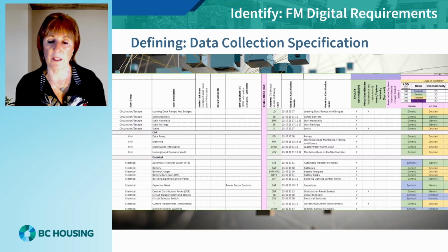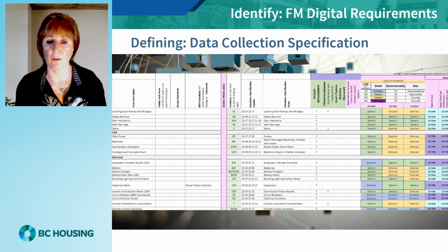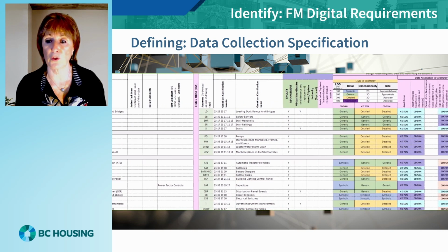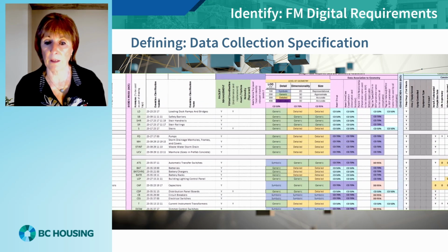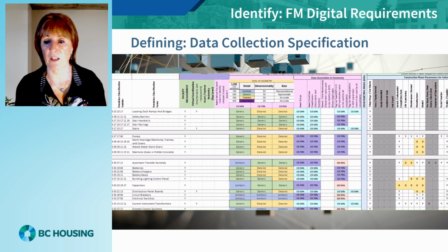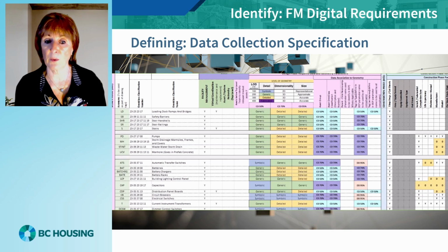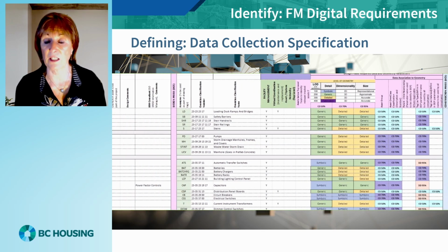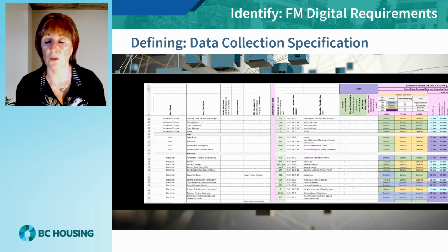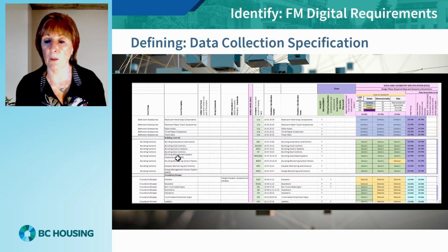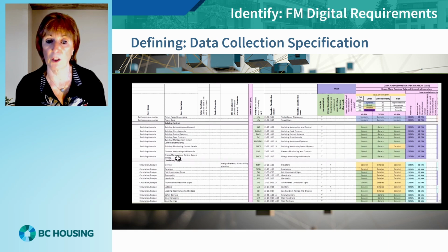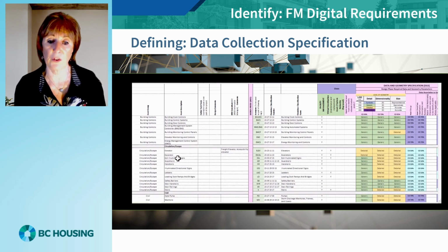Asset Information Requirements, AIR in the language of ISO 19650. You need to define what assets and what information, the data fields, are important to you during design, construction, and for facilities management. At Summit BIM, we have developed a Data and Geometry Specification, a DGS, combined with a Data Collection Specification, a DCS, that defines the assets, the use, the minimum required geometry, the required data fields, along with the time by which the information must be available in the model dataset to drive the defined uses.